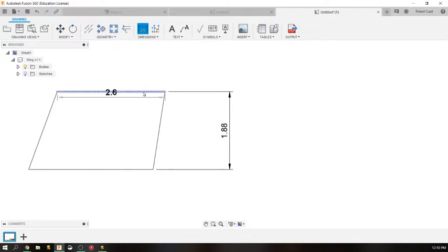Okay? Remember, you can always just select the line too. It makes it 10 times easier. You don't have to select those points. I know a billion people are going to forget this too. To do an angle, you select one line, you select another line, and then you can auto-adjust where you want that angle to go to. People are going to ask me that, I guarantee it.